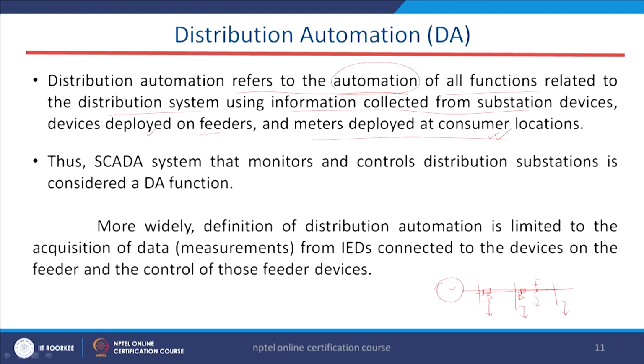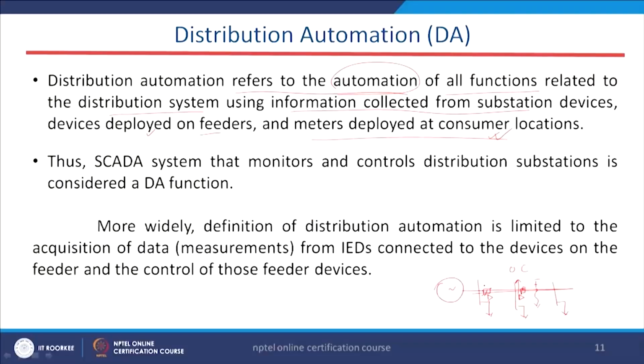So, if it is, say, an overcurrent relay, the relay will see that the current is beyond the set value of the current, the relay will react, it will give a trip signal to the circuit breaker. This is the circuit breaker, this is also one circuit breaker. The circuit breaker basically opens the section.